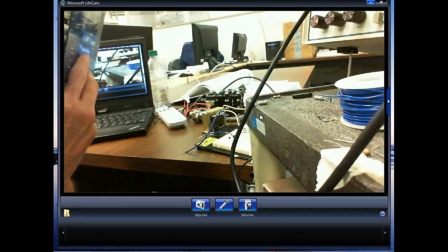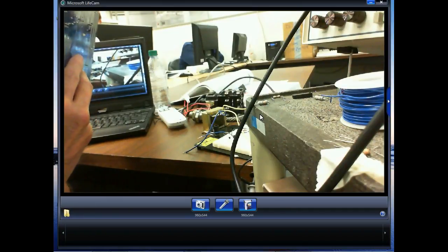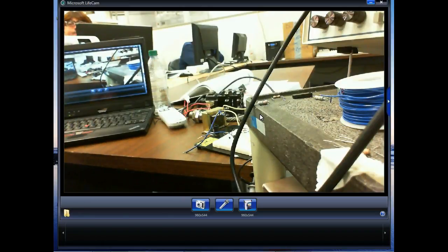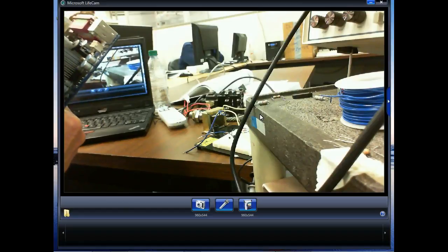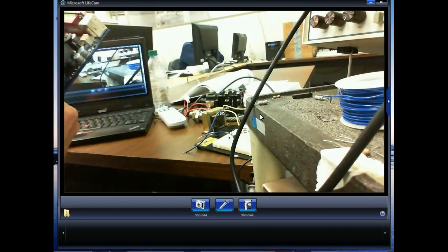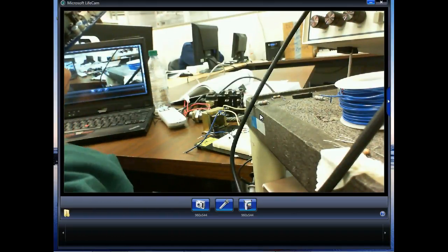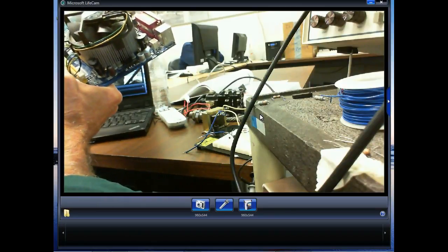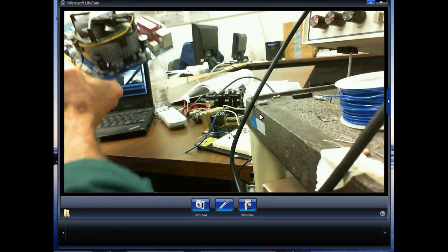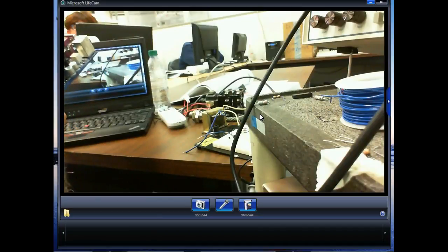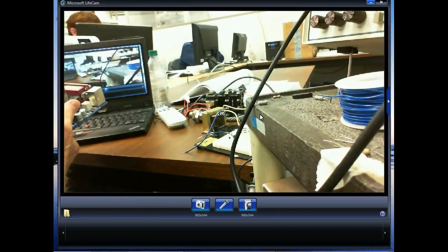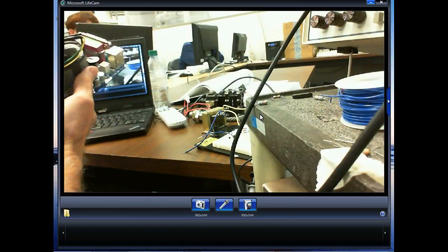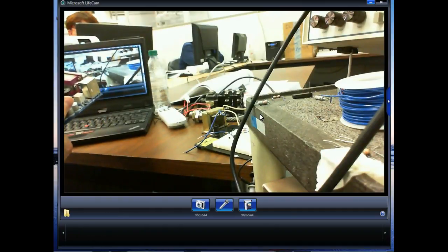So FETs are susceptible to damage by static discharge. So when we get into CMOS, we'll show some of the safeguards that we use to prevent static charge. So normally these things come packed in an anti-static bag. And then we have anti-static mats that we put the stuff on, and we can show y'all those. We put anti-static bands on our arm to work on these. And as long as you take just a few safety precautions, you're not going to damage them.